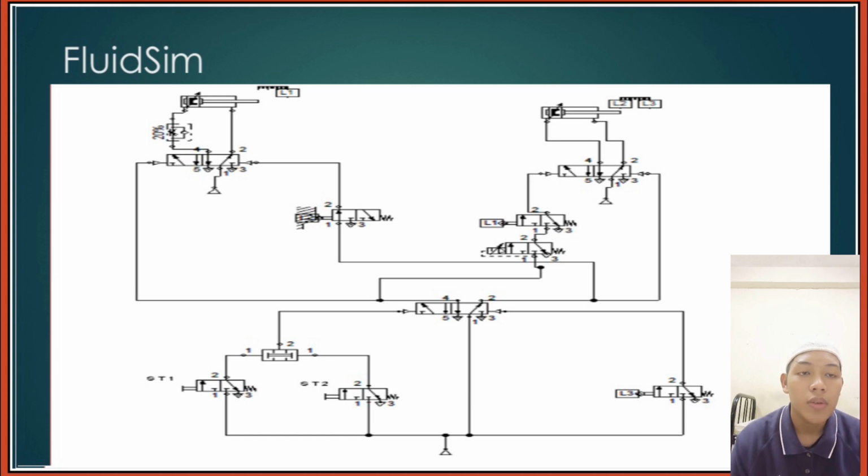So the valve A1 will trigger, and then the timer also triggers. The timer will start for 5 seconds. After 5 seconds, the timer will extend the DCV, and the drill bit will extend. So it will touch B1. The valve B1 will trigger and retract the DCV.